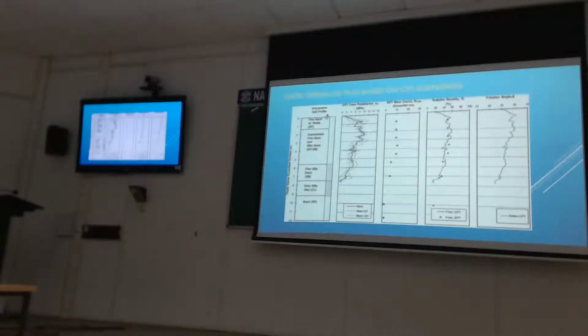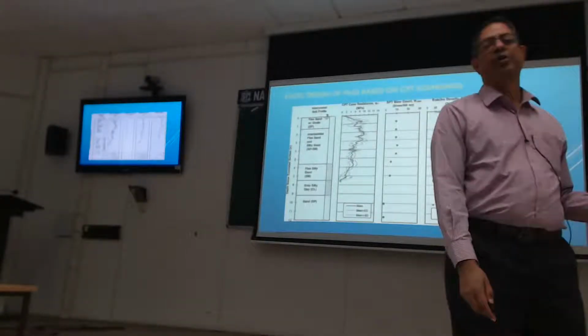Now, once you got these, if you follow the work of Robertson and Wright and other people, they have correlations from CPT to everything in the world, including your mother-in-law. So they have a correlation to get the relative density with them. They have a correlation of the CPT to friction angle. And people have made careers, Paul Main and the rest of the lot in the States, basically made a living on doing CPTs and converting them into something they think the industry wants. And you will take them with a pinch of salt, but those correlations exist.